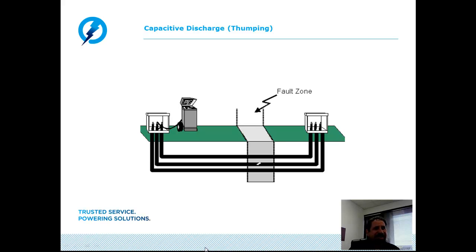In some cases, it may take hours or even days to walk the cable and definitely locate the fault. During that time, the cable is exposed to high voltage surges. A few years after polyethylene cable began to be installed underground, evidence began to surface that due to the aging effects of treeing in the cable insulation, high voltage surging for long periods of time was doing more harm than good, leading to a higher rate of repeat failures on these service-age cables.